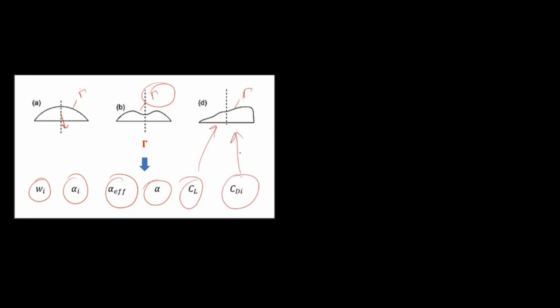And here the idea is that we are going to find a circulation equation for all types of distribution. Once you know the circulation, from this we are going to find the downwash on the wing. From that, the loss in angle of attack, then the effective angle of attack, then the overall angle of attack, then the lift and drag of the wing, then the induced drag. Using potential flow, we cannot find the overall drag, but this drag is induced by the lift. This component alone we can find using potential flow, thin airfoil theory, wing theory and so on.